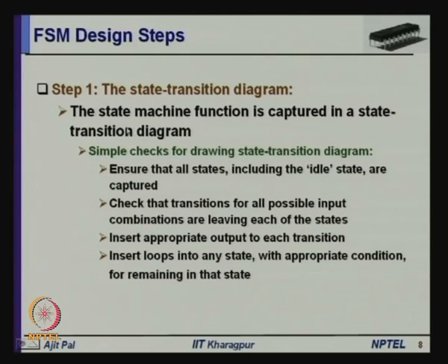Now, why are you actually realizing a state transition diagram? Because the state transition diagram captures the state machine functionality and the different transitions very nicely. Whenever you create the state transition diagram, you have to do some simple checks. You have to ensure that all states including the idle state are captured. Number 2, you have to check that transitions for all possible input combinations are leaving each of these states.